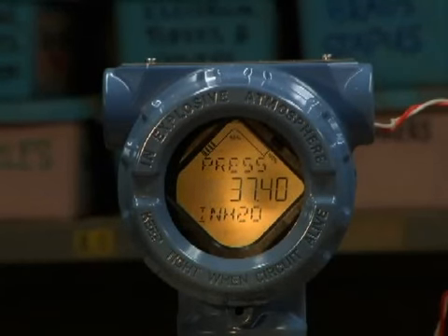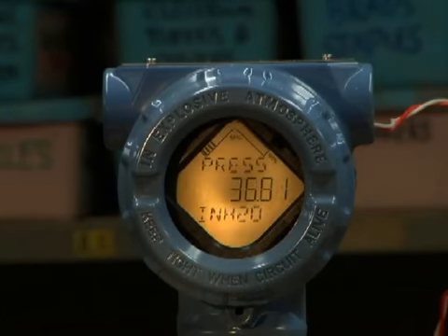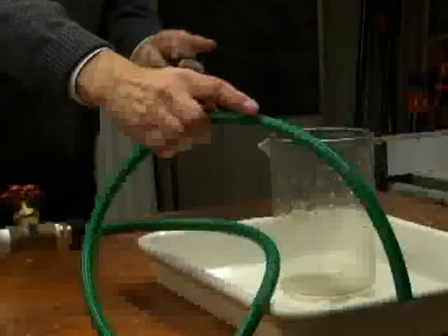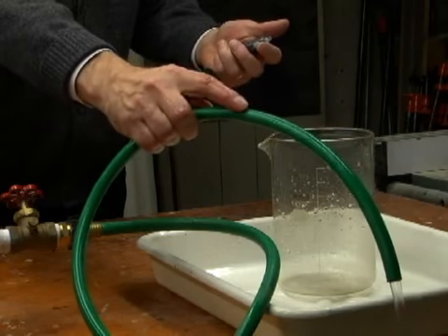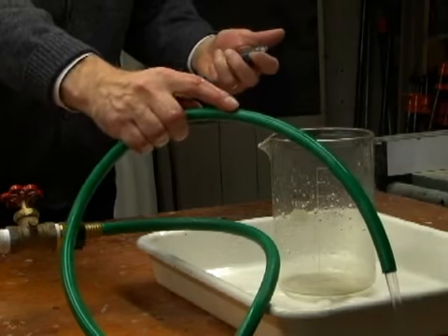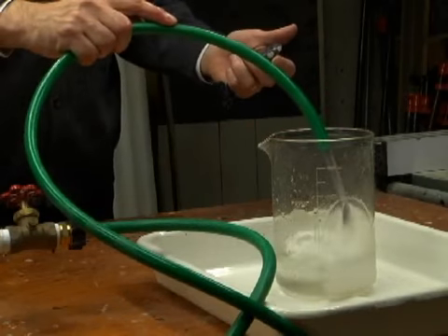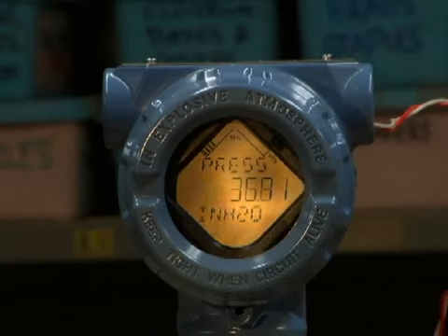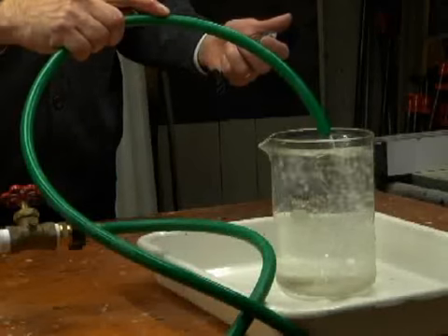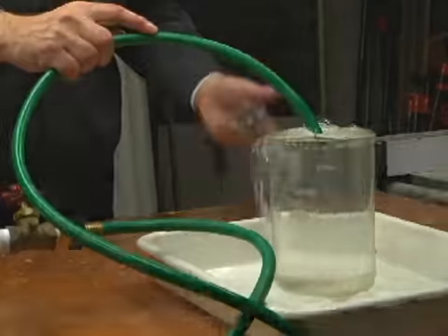So we've opened our valve and we're getting a higher flow, so our differential pressure reading has gone up to just over 37 inches. Well, right about 37 inches. So let's do a second calibration and see what we get when we're at 37. Okay, we're flowing again and we're stable. So let's see how long it takes to fill our beaker. This time it took just over 9 seconds.